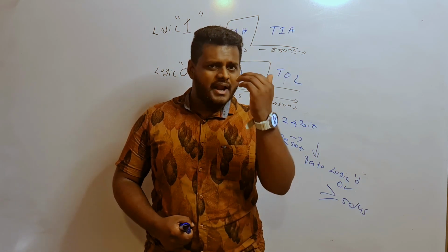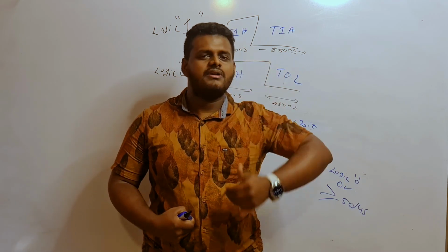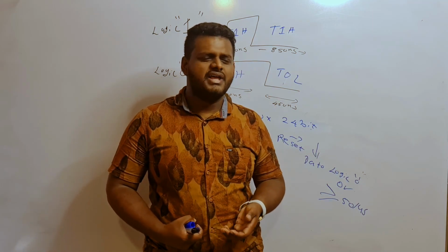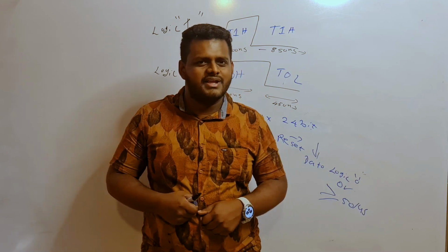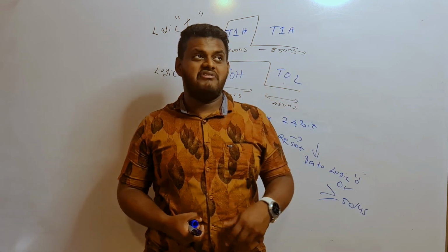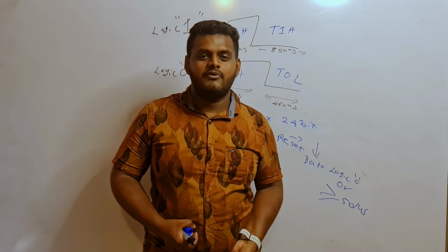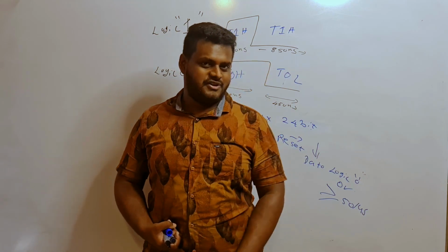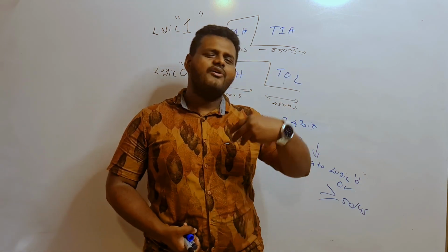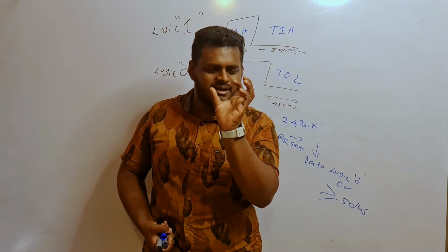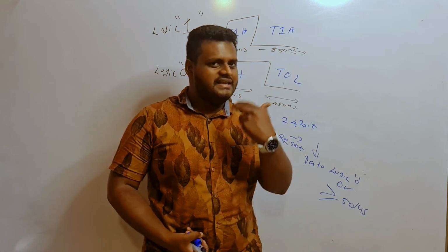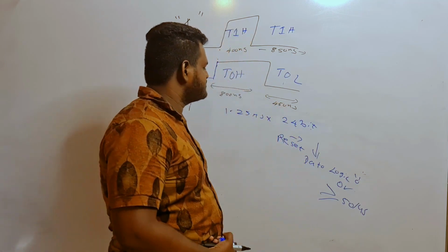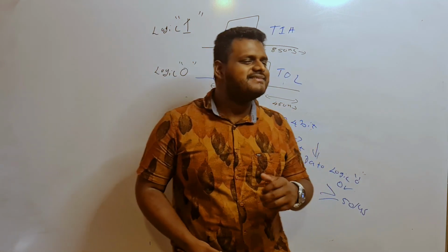So you have 150 nanoseconds total tolerance. Don't care about the 850 and 50 nanosecond values, because we don't have an AVR with a higher 4x PLL, so we cannot produce 50 nanoseconds. We have 200 nanoseconds minimum, the instruction cycle, not the clock cycle. So that is the way.